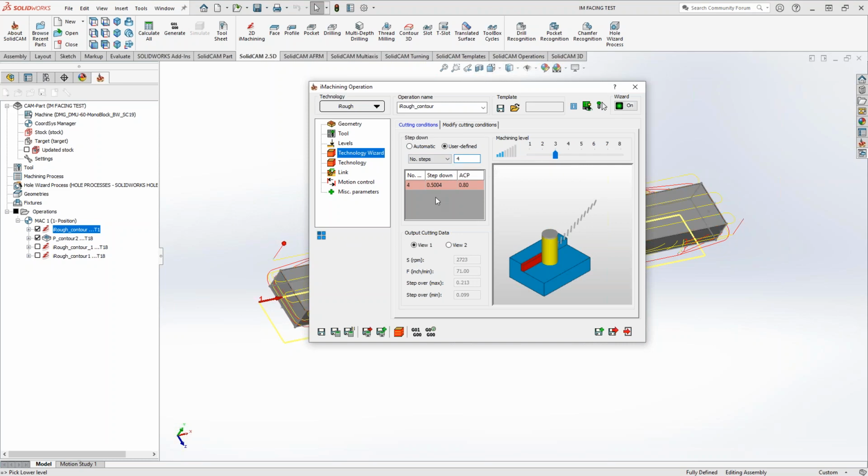I would actually say you probably don't want to do that even more so, because if you are tricking it into the geometry of the tool, that's going to mess up some of the material engagement calculations as well. So if you do have that 2 inch depth of cut with a certain flute length, helical angle, define that as is, and then, like Kevin's saying, come here and give it the step down.